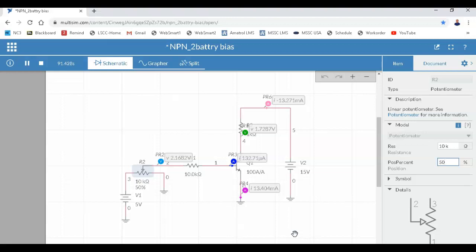So what voltage would we measure across our transistor? This resistor right here is dropping voltage, and this is the voltage drop across the transistor, guys. Because look where I'm taking my voltage measurement. I'm putting it right here. Can you see what I'm talking about? If I'm taking my voltage measurement right here, relative to this guy right here, then that is 1.72. So is it in the active region? Is it cut off or is it saturated?